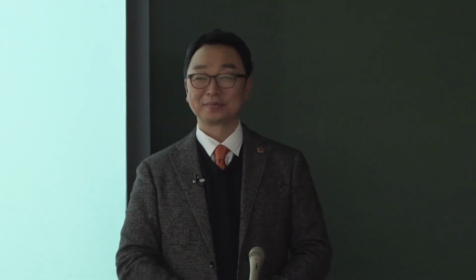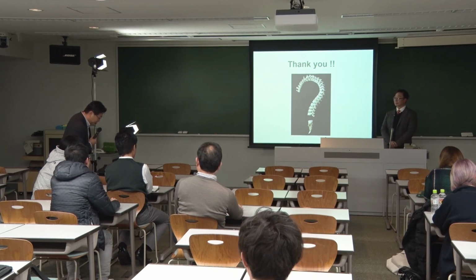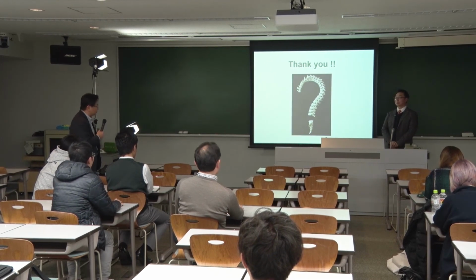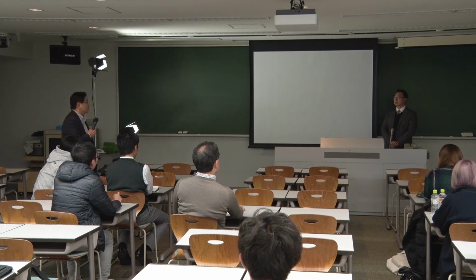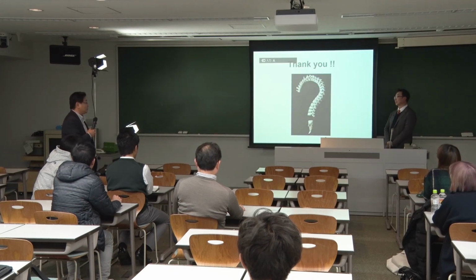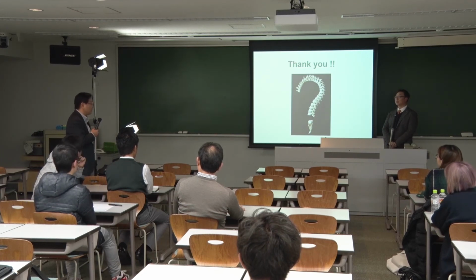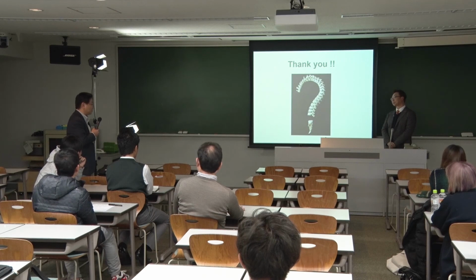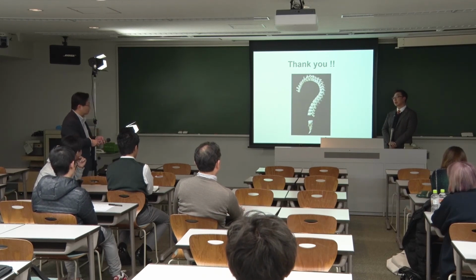Any other questions? Okay, may I briefly ask a question? I'm interested in the BR, is it buckling ratio? Buckling ratio, yes. Why do you divide R by thickness? Well, if R increases, then it's more resistive against the bending moment, right? Yeah, in terms of section modulus. Same for the thickness as well. So why do you divide R by T?